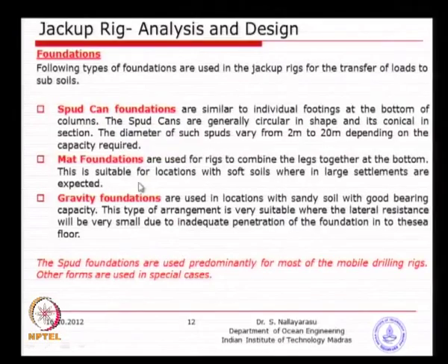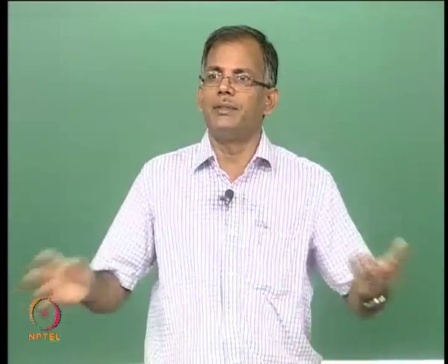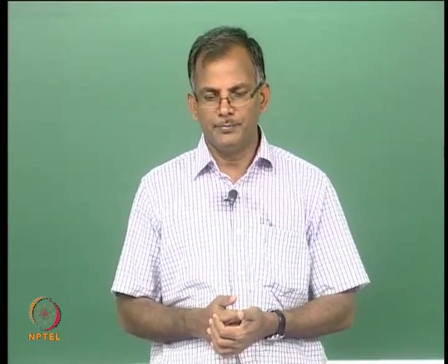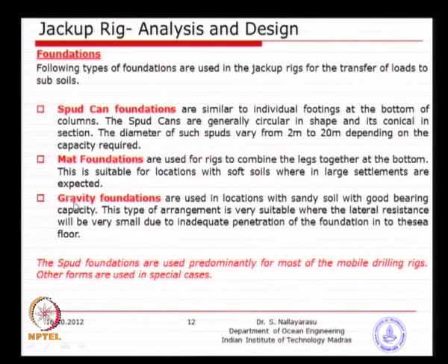So, this mat type of foundation is very useful whenever you have very soft clay, because if you allow the soil to squeeze away, then the bearing capacity will reduce. Instead, you make it a complete slab and do not allow the soil to squeeze away, then you will get a better capacity.